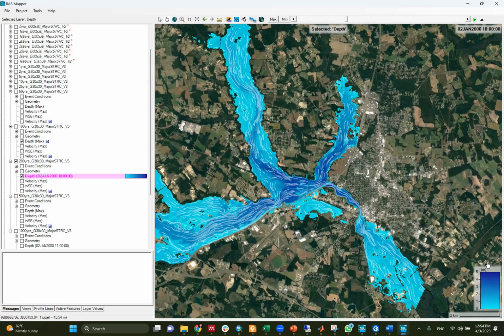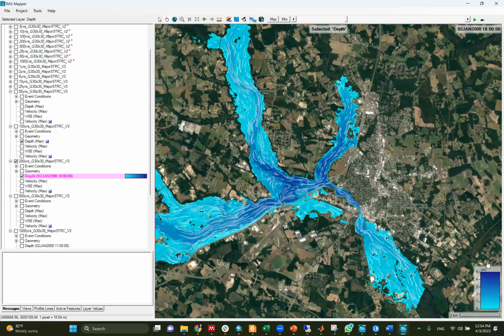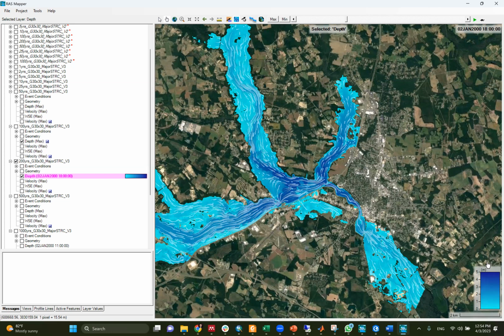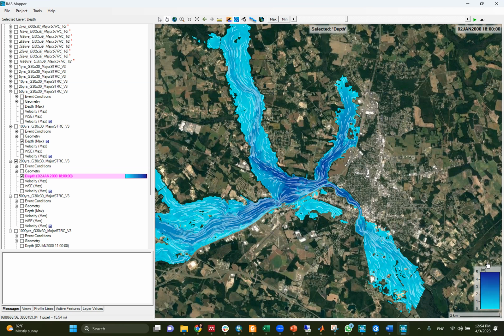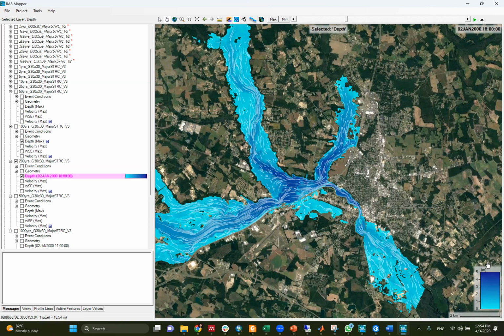Same thing in flooding. What if we are assuming that the TV is on a table? What if we put the TV mounted on the wall? We are assuming that the AC unit is resting on the ground. What if we raise the AC unit by 1 meter? Let's assume that the household has 1 day of warning. What if they were able to elevate the electronics? So I'm going to ask you to rerun the fragility. I'm going to give you another set of curves that you will use that has the mitigation impact embedded in it.